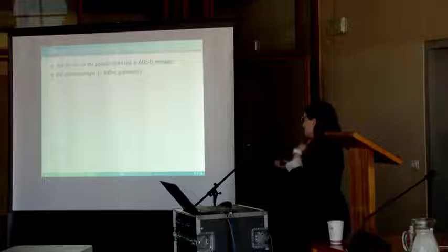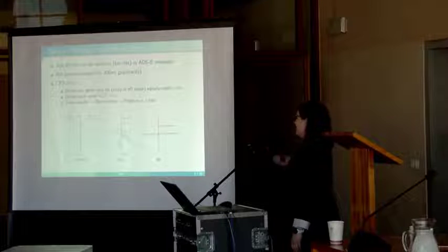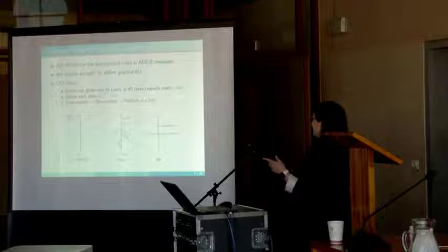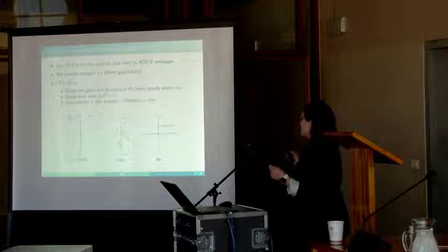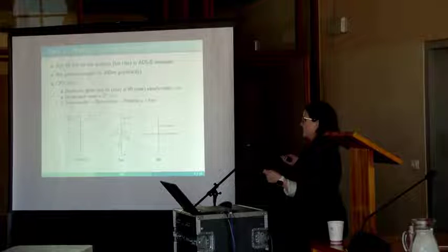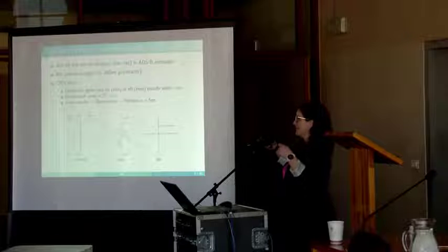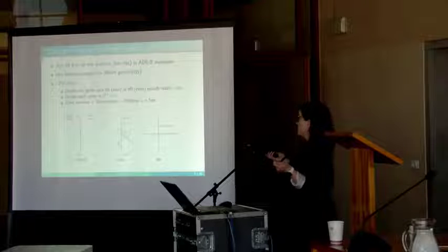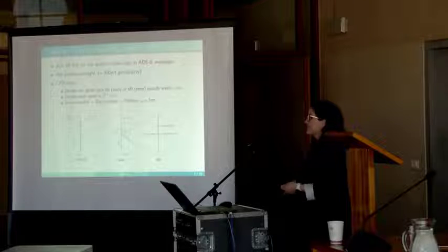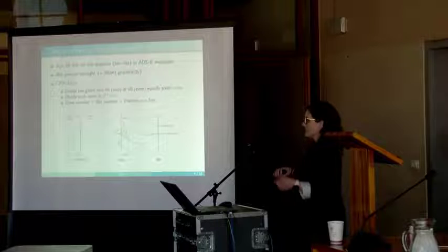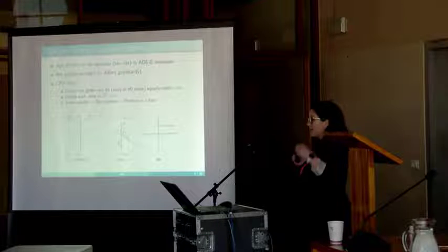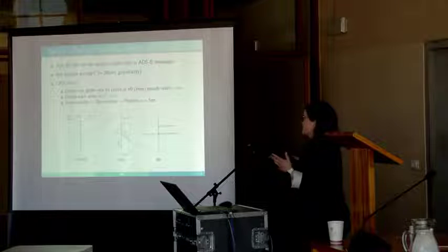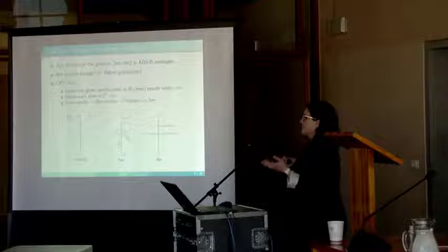So this is not precise enough. The idea behind CPR is to divide the globe into zones. You have two different kinds of encoding, an odd encoding and an even encoding. Depending on this, you divide the globe into 59 or 60 equally sized zones. And then you divide each zone into 17 bins. Then, with the zone number plus the bin number, you can imagine this as a small square of 5 meters by 5 meters, and this will correspond to the position of the aircraft.